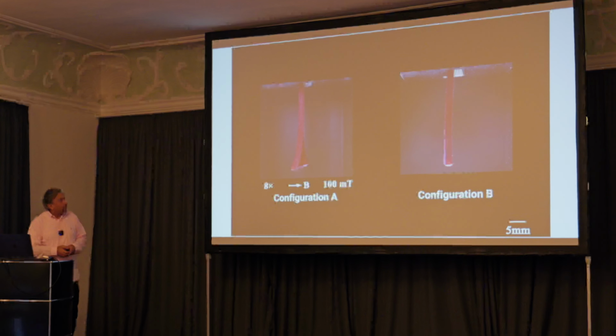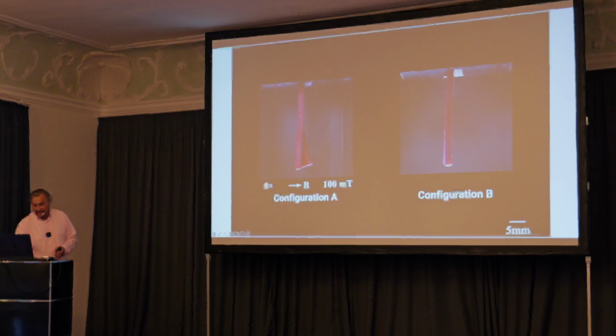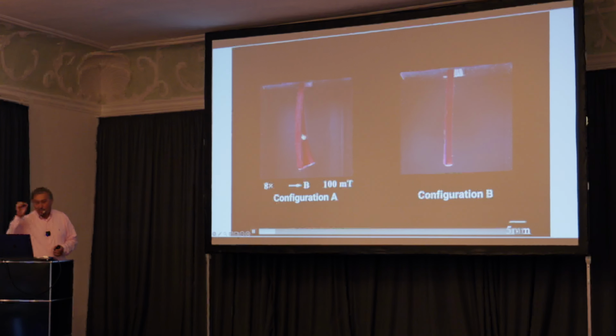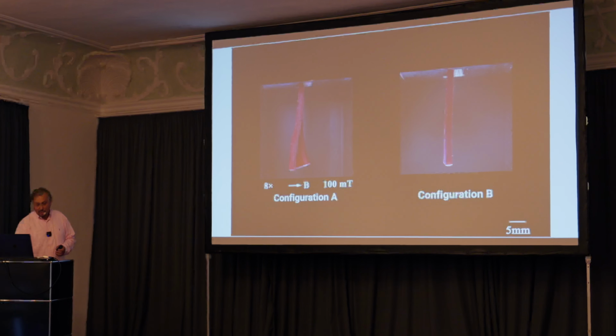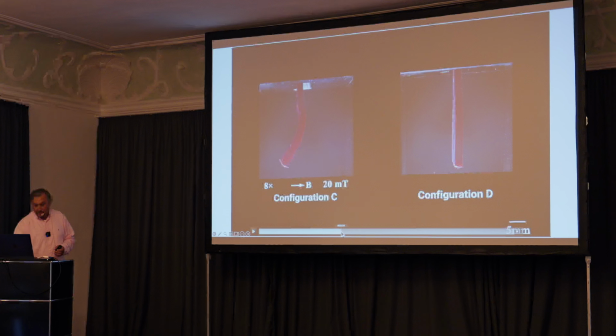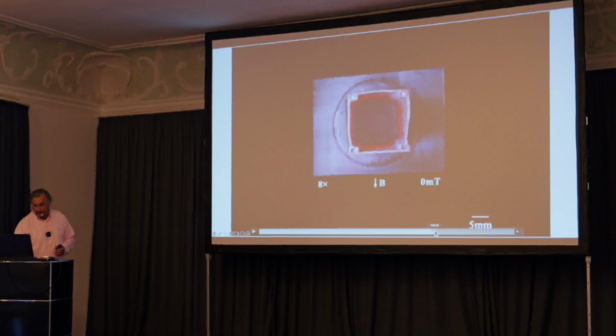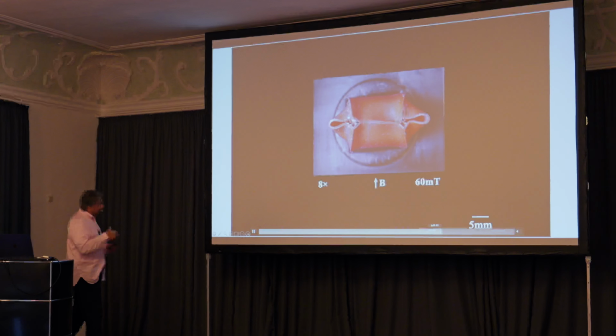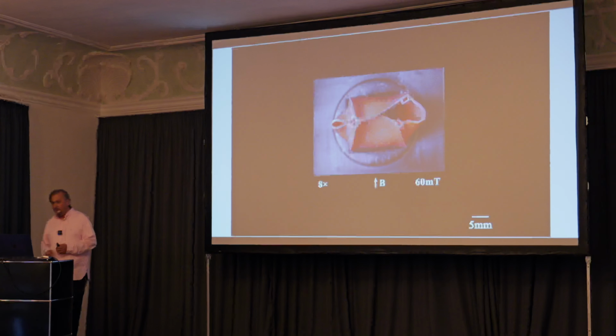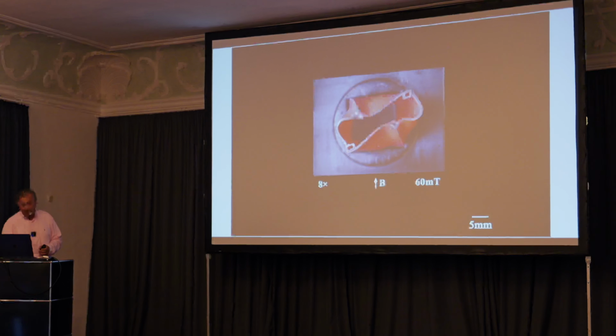We can also go more 2D and 3D, again, all enabled by inside tubes that have been actuated with different modalities. Let me just move faster here. So these are all different configurations. We can get very complex deformations nowadays, as you see, and we can even go fully 3D. In the last example, the reviewers wanted more complexity. So we can now have a 3D, fully reconfigurable actuated soft structure that is enabled by these actuated magnetic rods inside.